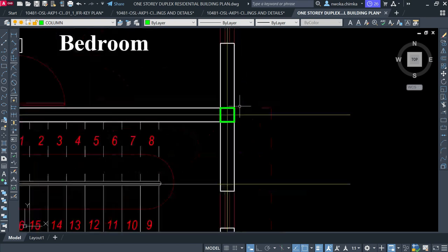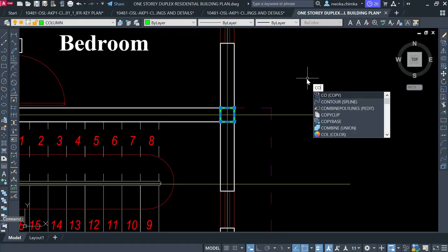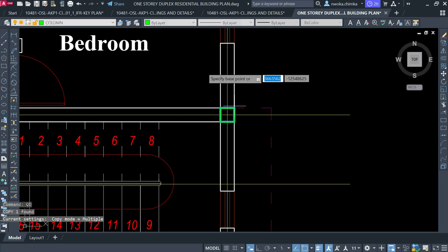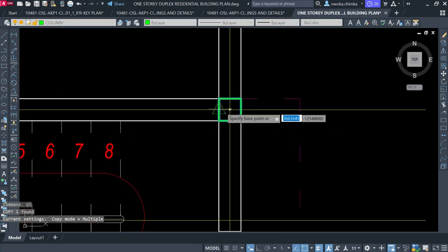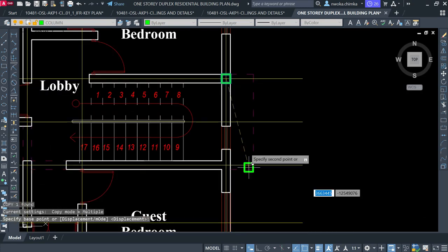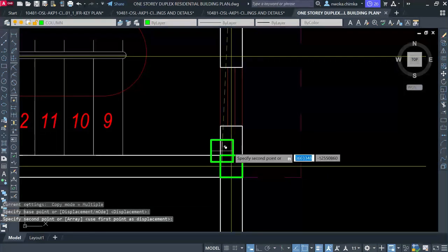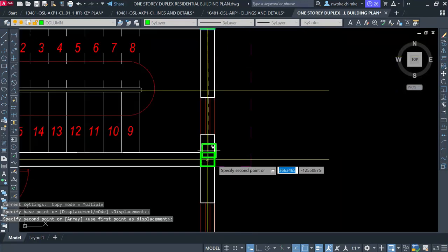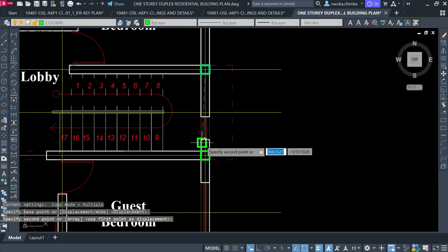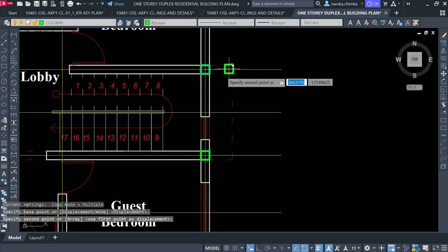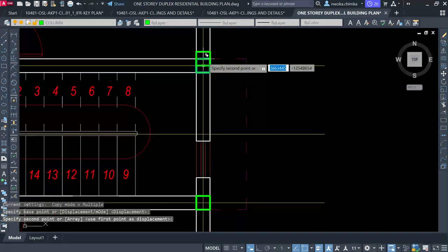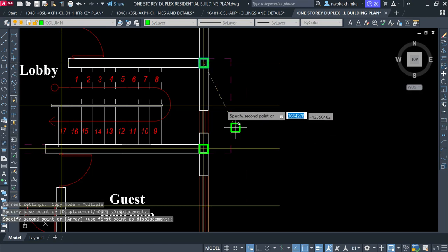Okay, so since I have a cantilever here right now, I'll just put a column at that point, which I've put, and I'll also copy the column again and come to this point where my cantilever ends and put one here. But since this cantilever length is not that long, I think this is just 600, I can choose not to use it. But I'm just telling you the principle: if you have a cantilever, you're meant to have columns at both ends, as you can see what I've just done.